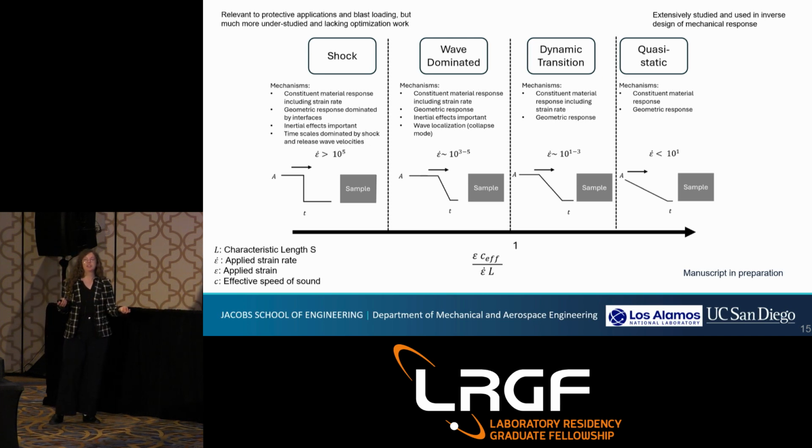where the constituent material response starts to have some strain rate effects, but you're probably not engaging inertia of the lattice itself deforming because you don't have localized behavior yet. Eventually, as you go lower than 1, you enter a region in which you have wave-dominated behavior, in which inertia effects start to gain importance. And then eventually, if you keep going very, very low, which is outside of the scope of this second project here, you will enter the shock regime where things start to change even more.